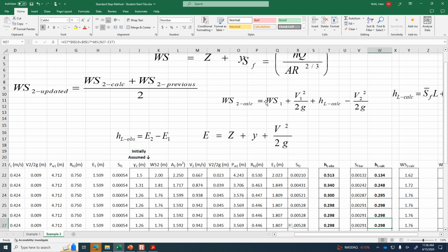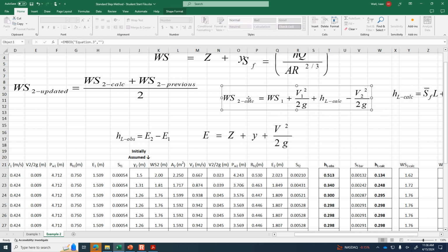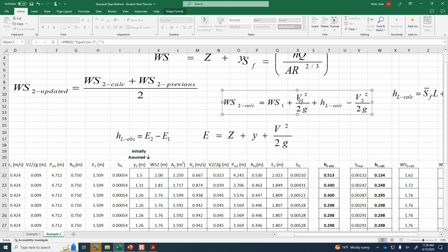It's because when we were doing our calculations, these water surface calculations already take the Z into account. Like the adjustment engine that's working in the background, this water surface has the Z's built in. So it was just the indicator. The reason we calculate this head loss is as an indicator. It's not because this value is being referenced elsewhere. It was the calculated one that was being referenced, and that one didn't rely on the E2.